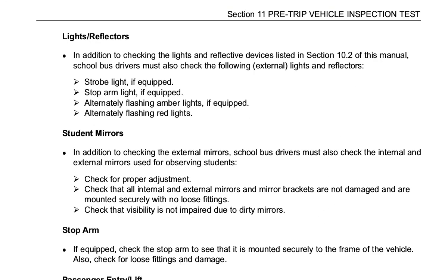Lights, reflectors. In addition to checking the lights and reflective devices listed in Section 10.2 of this manual, school bus drivers must also check the following external lights and reflectors: strobe light if equipped, stop arm light if equipped, alternatively flashing amber lights if equipped, alternatively flashing red lights.